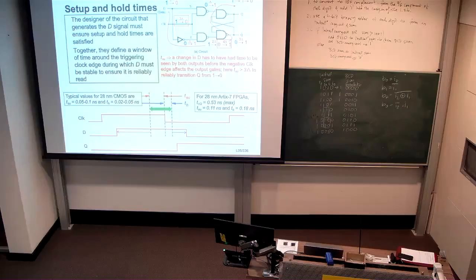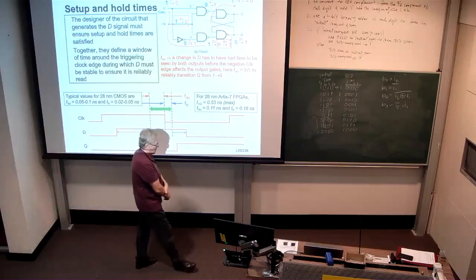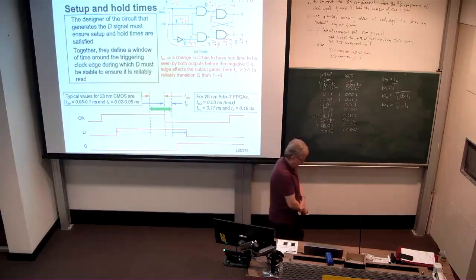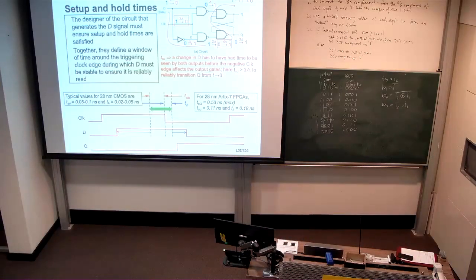So that means if you're operating the device at faster than, what, 200 megahertz, you might not even see output changes before it actually gets a new input and therefore has to change the output again, right? Because it's taking half a nanosecond here for that change to occur.